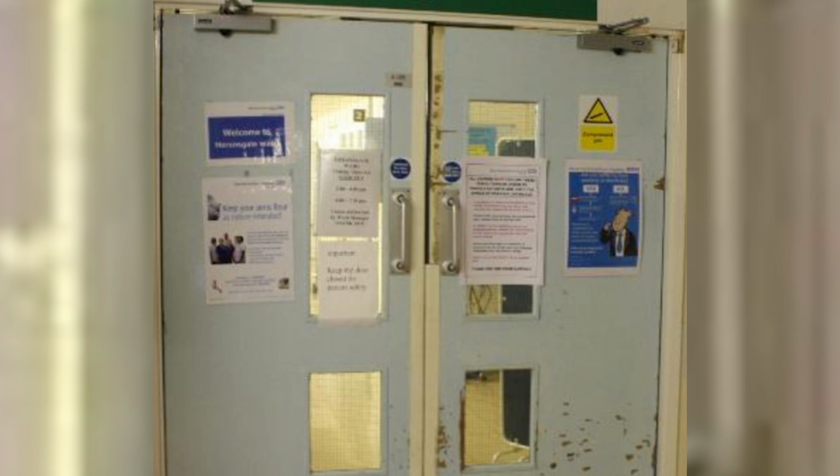In this slide, you can see fire door damage. Now, this is a commercial fire door, so it's slightly different, but as you can see, it's got multiple chips to the wood. The glass panel is actually cracked below a sign that you can't see, and the strip that sits along the right-hand side of either door edge is partially missing. So this fire door is defective, and in the event of a fire, it won't work.